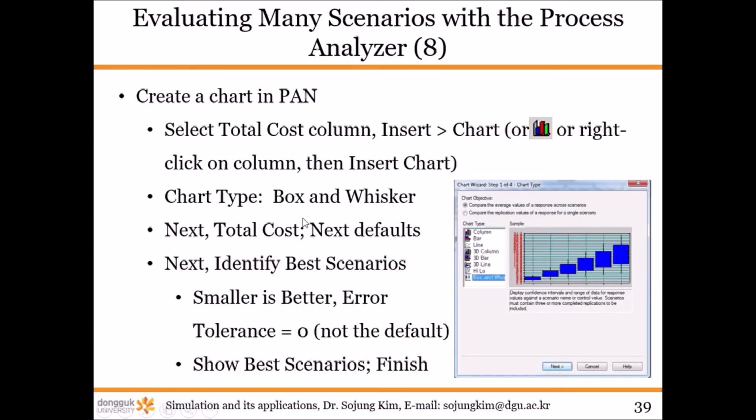Once you have a result, you can also create a chart in the process analyzer by selecting the insert chart menu. There are several chart types, and you can choose the box and whisker if you want. According to the instruction, you can develop the box and whisker.